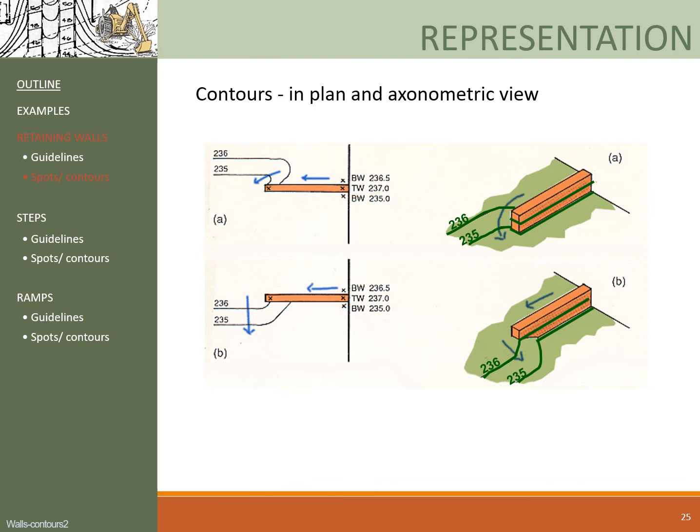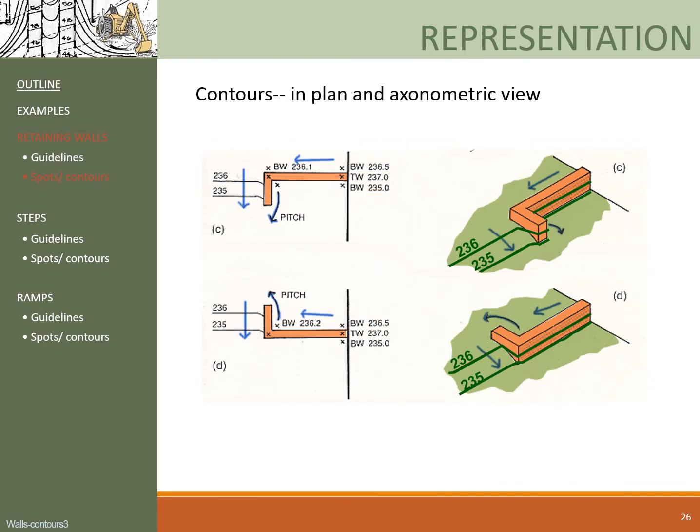However, an important skill that we develop through this course is the ability to visualize where the contours go along the wall, even though they don't physically show on the drawing. Okay? Similarly, for the angled walls, the contours on the plan stop when they hit the wall. It's important to recognize that they connect around the wall because eventually you need to know how contours connect in the surrounding landscape off the wall. So knowing the connection points here will be really important. Okay?